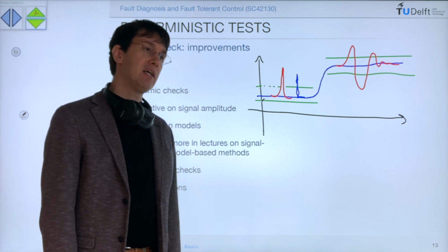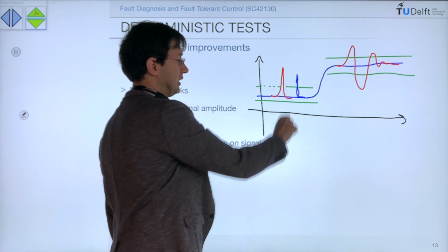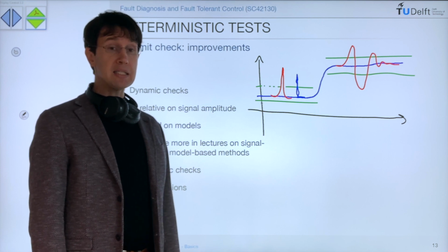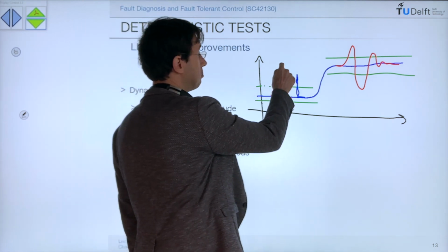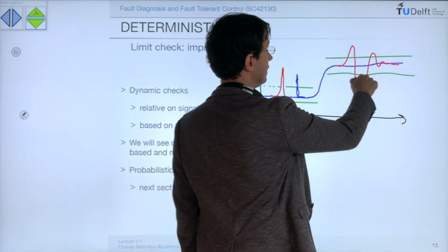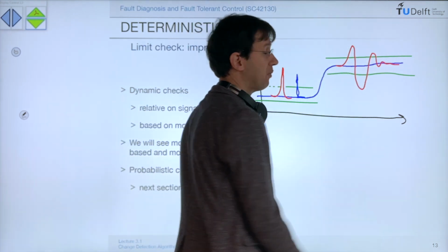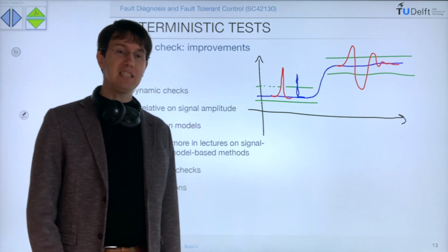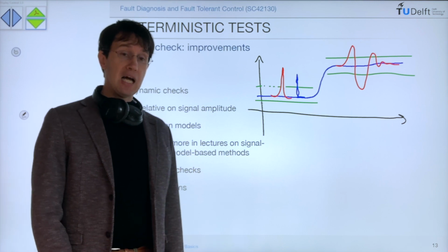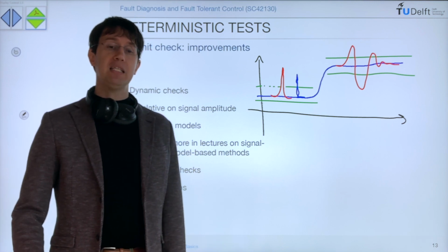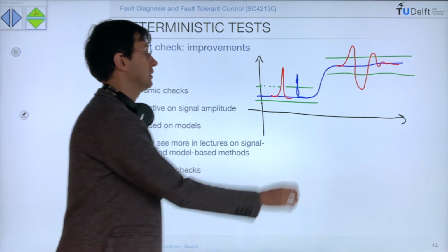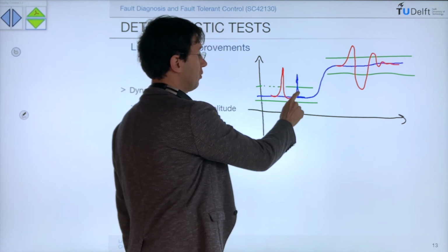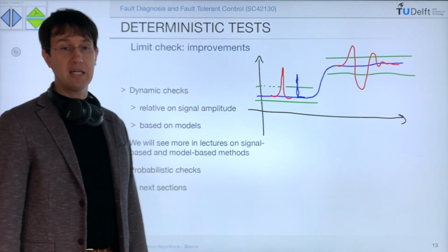So you want a way not to be always alarmed by these very short and very common events, and instead to be alarmed when we have something that is big and lasting enough, like this and this. These two things are quite unlikely behavior for a healthy system. And probabilistic limit checking approaches allow us to have a mathematically sound formulation to tell apart this red faulty behavior from this blue random, noisy, and healthy behavior.